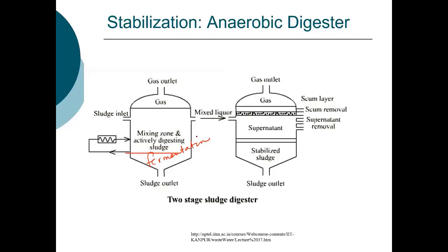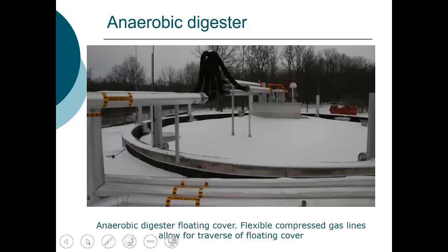It's mixed and it's heated. And in the second stage, the solids are separated. And you can see, so you've got the solids separating, you've got your scum layers, you've got your scum removal, gas on the top, and an active digestion zone.